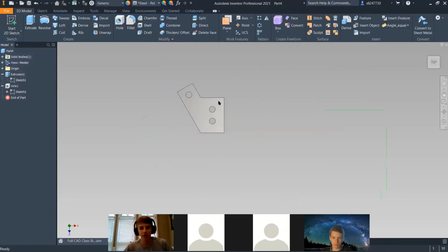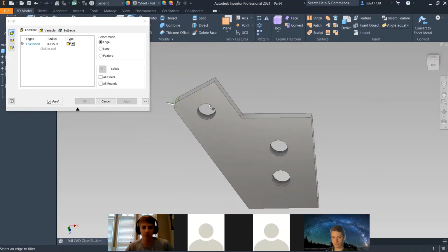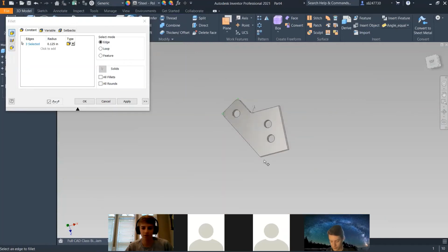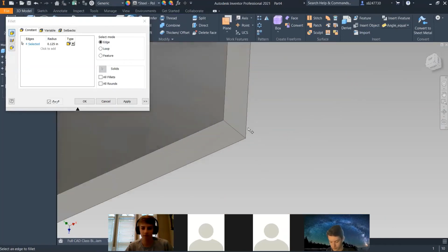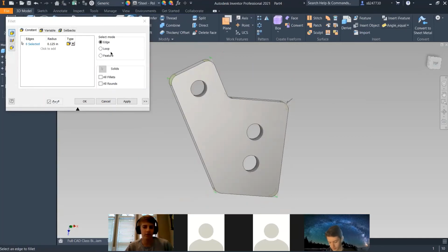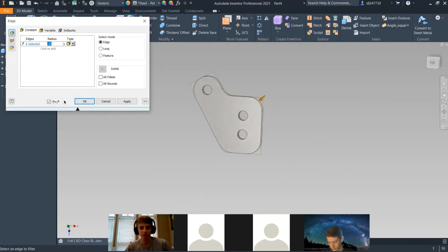There were holes there. So this bracket right now is kind of chunky. So what we're going to do is click fillet to make it look nice. And this time we're going to use an edge. So we want to fillet this edge, this edge, this edge. In real life, this would be using like a belt sander. So let's try 0.25. That looks pretty good. 0.5. About 0.3. That looks a lot.